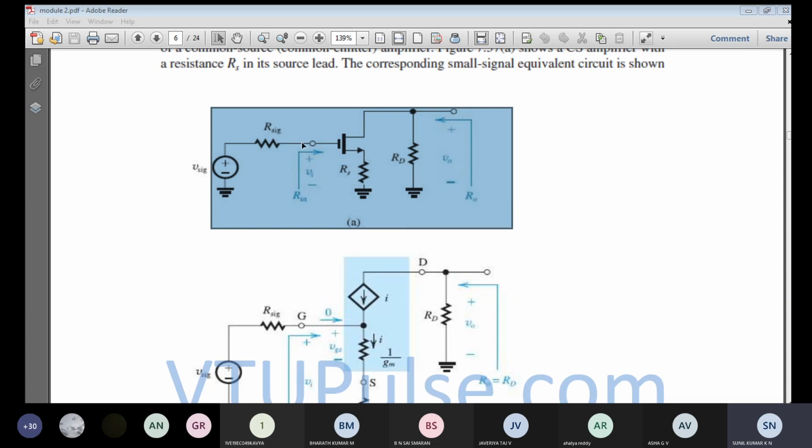What we are going to do is, from this small signal model, add another constant current source. What is this Gm into Vgs? This is the current that is flowing between drain and source. So if I am going to connect another Gm into Vgs, that is another current, is there any change in the terminal current?